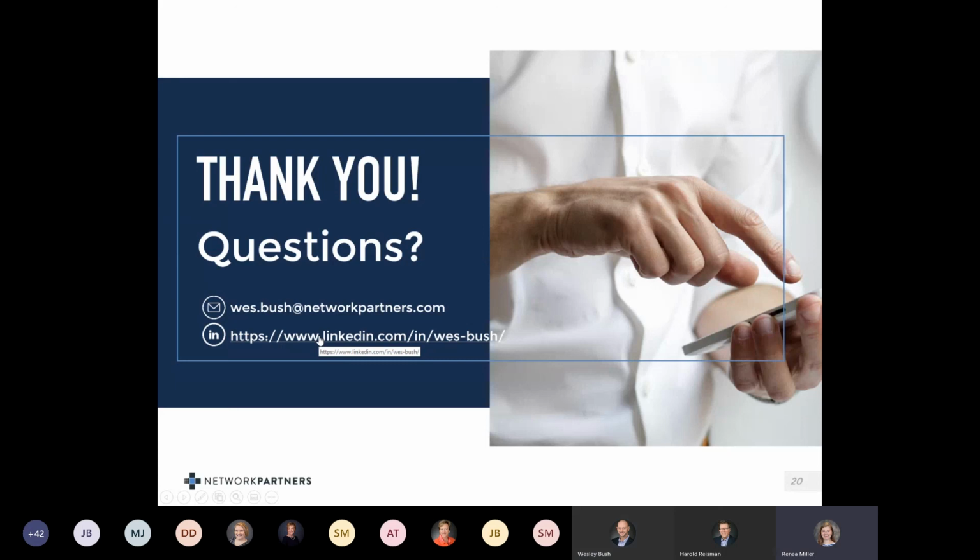The last question we have so far is, what would be the ideal sample size for feasibility testing? Realistically, the ideal sample size would be whatever you would typically do for your final design verification test. That's ultimately going to provide you the most confidence in your design.